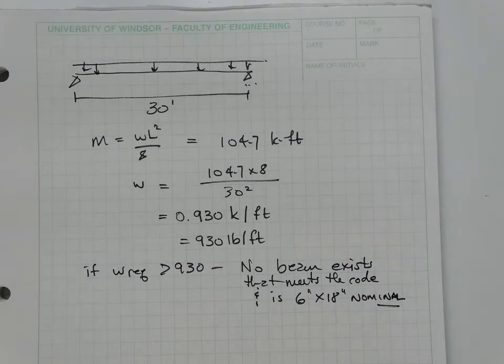I'm going to build 2 beams. I'm going to build one beam out of reinforced concrete and steel. I'm going to use it to rho max, to its maximum limits. Then I'm going to build another beam that's 2 bars in the compression zone and 2 bars in the tension zone and nothing else. And that's going to work because I'm going to put those 2 beams physically in the same place.